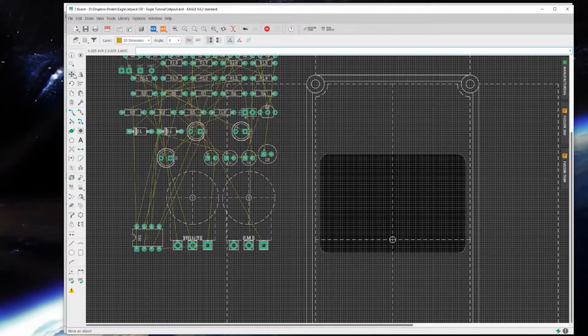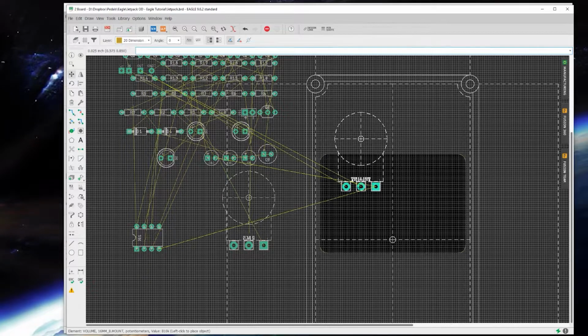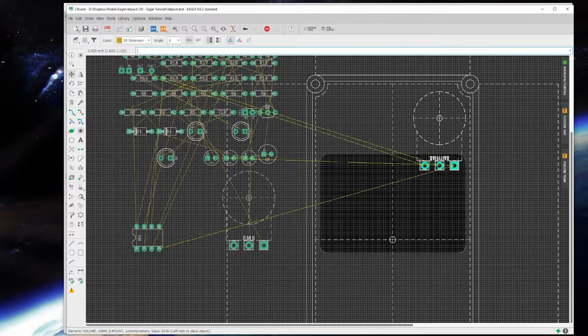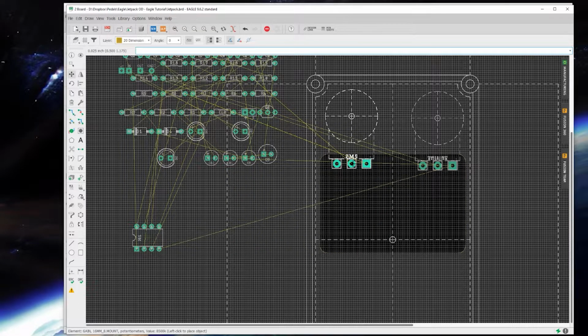I'm going to go ahead and place my pots, because that's the other thing. With this one, it's fairly straightforward, since it's just 2 pots and the external LED indicator. And remember, you are looking at the bottom side of your enclosure in this view, unless you're getting fancy with long pin pots or doing something a little extra. But generally speaking, this is how you're going to be working. So I'm going to place the volume on the right, which will be the left when you flip it over, and the gain on this side.